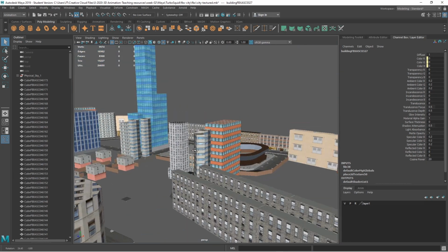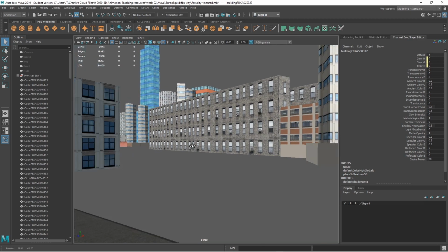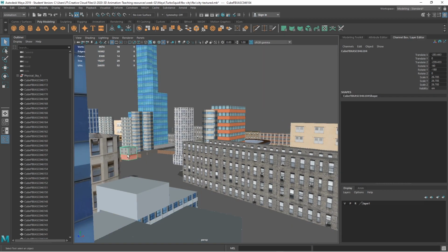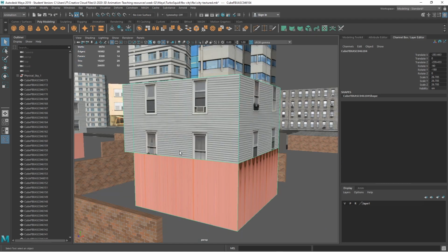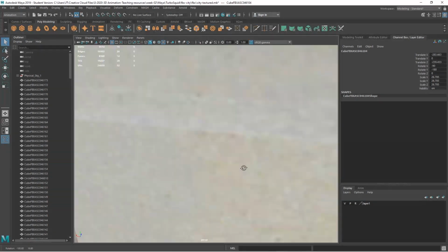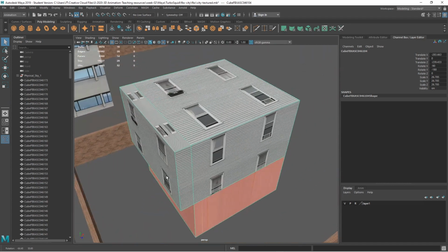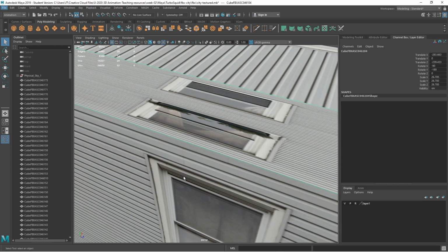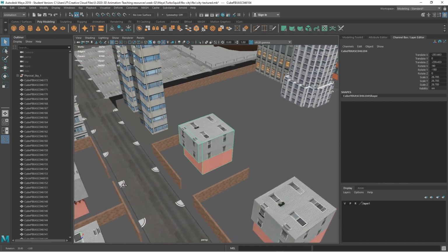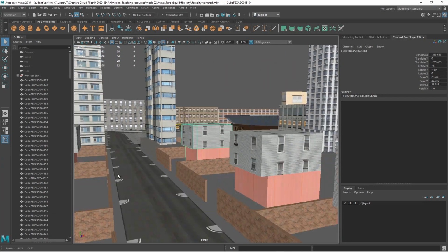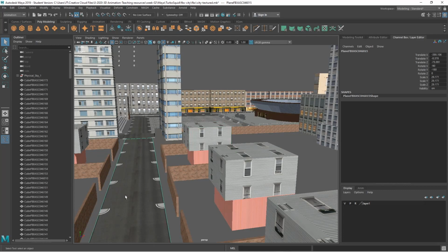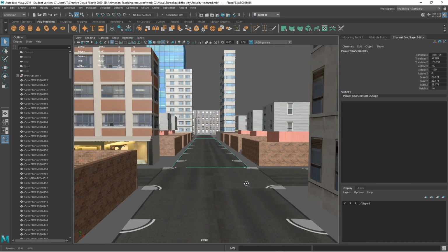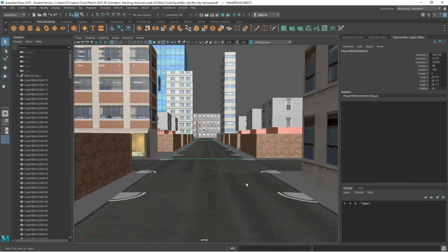So there's a lot of space in there, but as I move around, I'm just going to click on a certain object and press F. That brings it to the center of the scene and allows me to rotate around it. So that's a good way of setting up where you want your cursor to be, or what you want to look at. That allows me to come into this area, and if I wanted to focus on that street, I can focus on that as well.